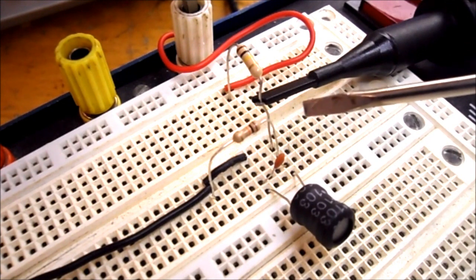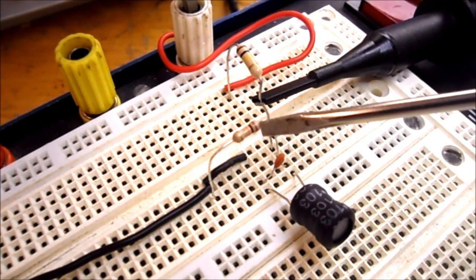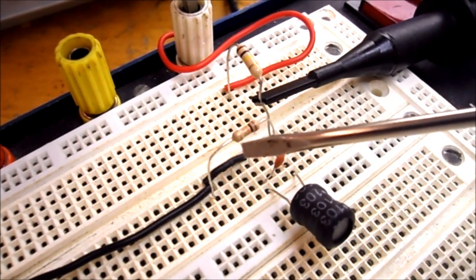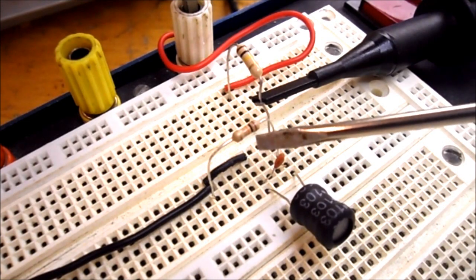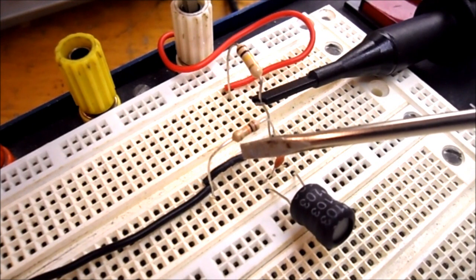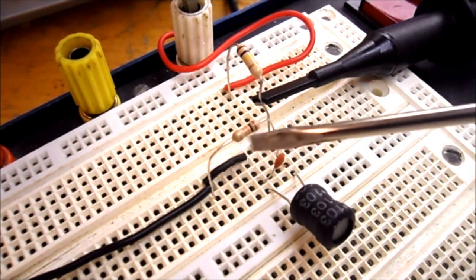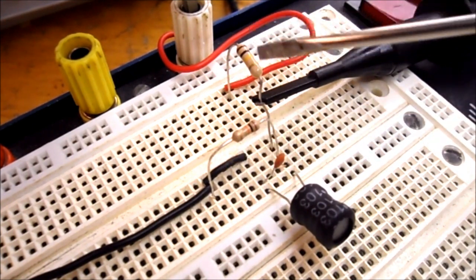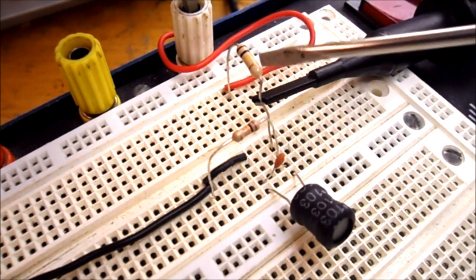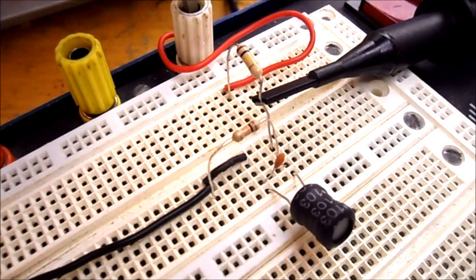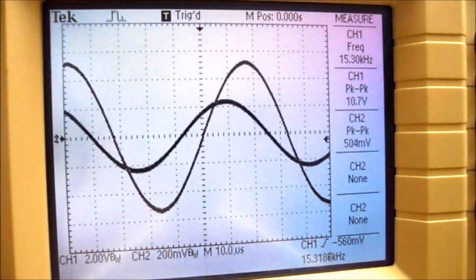So this is now my circuit, and I've swapped out RA that was 2.2K ohms. It's now brown, black, orange, so that's a 10K ohm resistor. Remember, you're switching out RA and not RS. RS still has to be the 100K ohm resistor.